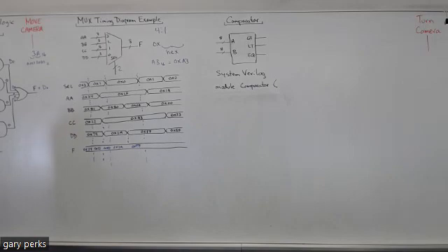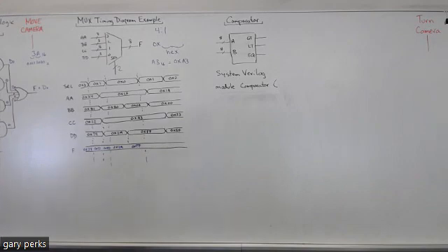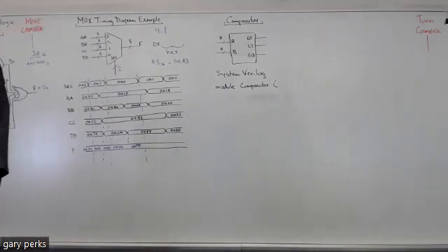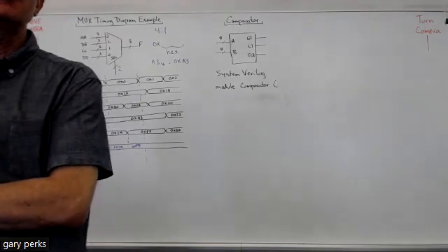Because in Vivado, just like in high-level languages, you can use if statements and case statements. Now, again, I want to stress that even though the if statements and the case statements look very similar or exactly like what you've seen before in other high-level languages, in Vivado, what you write are not instructions to a microprocessor like they are in a high-level language. You always got to keep in your mind that code, even though it looks like a high-level language, is code that represents hardware.